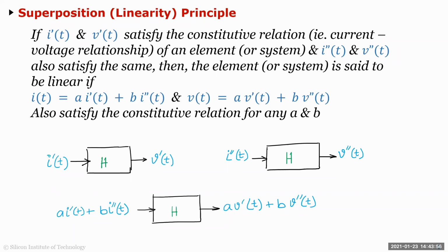Fourier is actually one example, right? If you take a system and once you know it's linear, you find out the frequency response. Then you know that for any arbitrary signal, because every arbitrary signal is a composition of sine waves, if you know the independent response of each sine wave, and you know it's a linear system, then you know what the output will be for every arbitrary signal. If it is not a linear system, then you can't assume that. So that's the superposition principle.